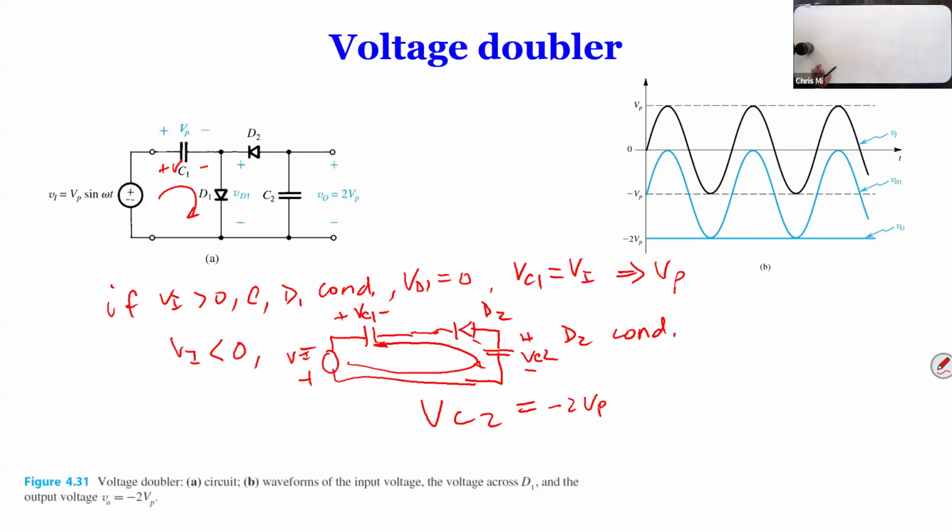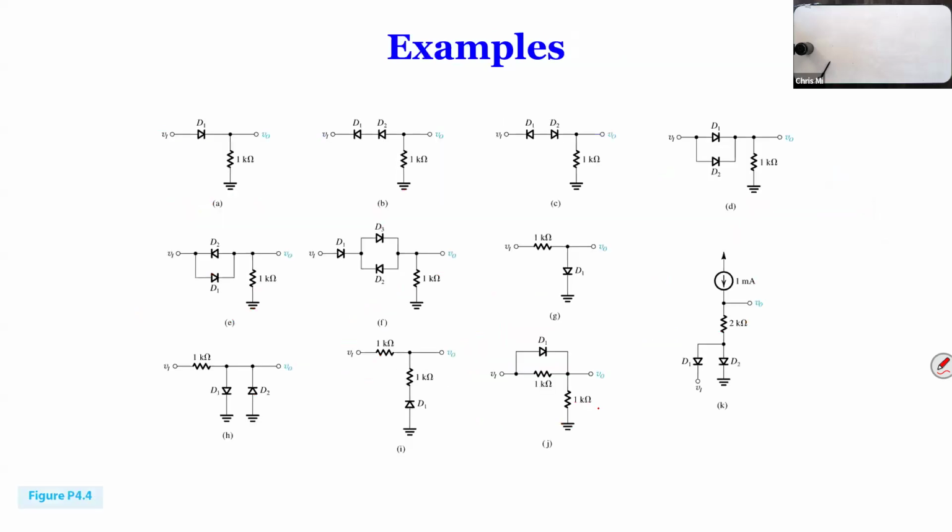So that's called voltage doubler. Of course, the output is actually negative, not positive. There's some loss in our capacitor when we switch to the other side? Here we are assuming every component is ideal, so really there's no loss. But in real life, of course, there's resistance inside the diodes, and there's also some time to charge the capacitors. So it's not going to be a perfect waveform. But of course, after this, you can use a super diode so that you don't care. They're almost ideal, right? So it really works very nicely.